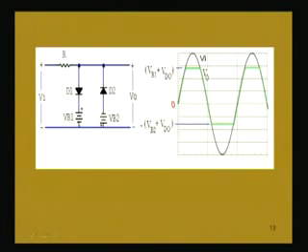So, V naught will be equal to Vi for this portion. Now, whenever Vi is greater than VB1 plus VD naught, the diode D1 conducts and the voltage will be equal to VB1 plus VD naught, that is why it will be constant. Then again, when Vi is less than this voltage, the diode D1 will not conduct and input voltage and output voltage are the same. It will continue in the negative half cycle.